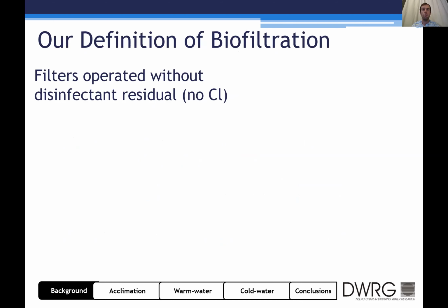And that can support a lot of active biomass just because there's a lot of substrate for them to consume. The Mackenzie River is relatively low in organics. We've been monitoring DOC for the last 2 years and see typically somewhere between 0.5 and 1.2 milligrams per liter. So a small fraction of what we would see in some of the other surface waters. And that really doesn't necessarily promote the growth of bacteria to the same extent that higher substrate loadings would.